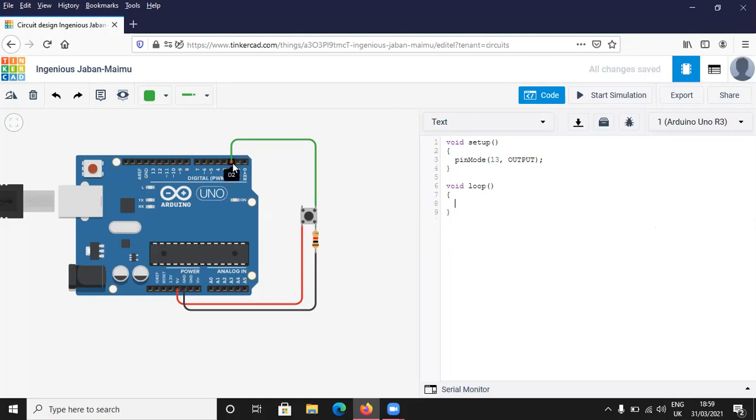So pin mode, we have one port, that is D2, which you have connected. So you can change this to 2. And then we have it as input because this time it's connected as a digital input. But again, we are going to print the value in the serial monitor. So I can do serial dot begin because we need to initialize that so that it can be able to display for us. And this value here is supposed to be 9600. So our serial monitor is initialized, and therefore it will be able to give us an output. Okay?